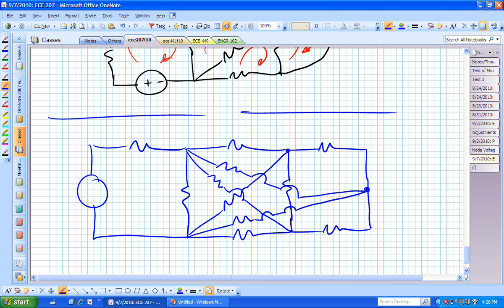Well, you guys are non-electricals. You're more visual. You can draw me better than I can. But if you try to pull those apart, you're going to see that you're always going to have something crossing. Meaning, for these circuits you will not be able to write mesh equations. You can't go around a mesh without crossing over. So this is a non-planar network.